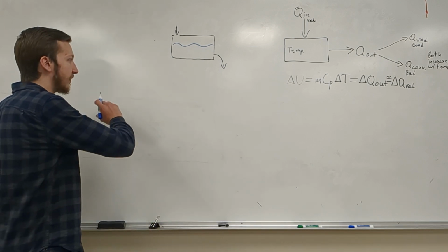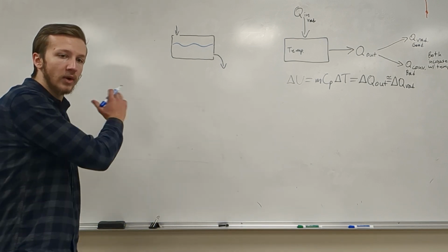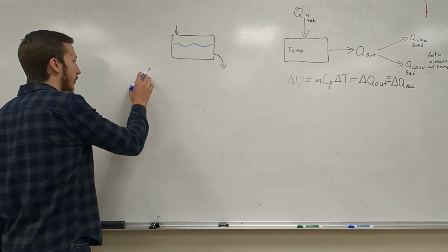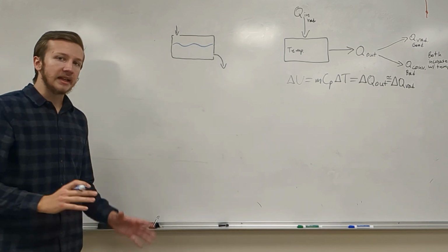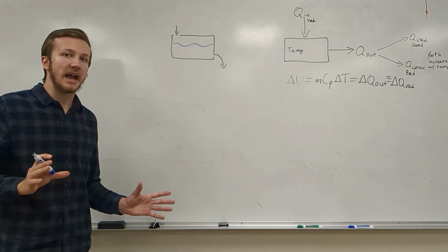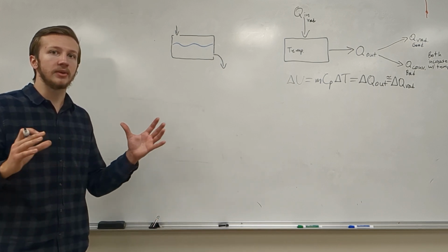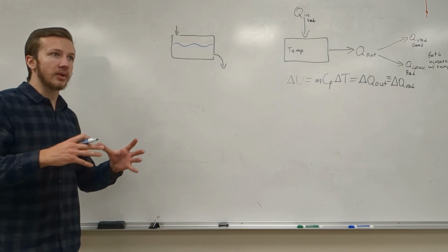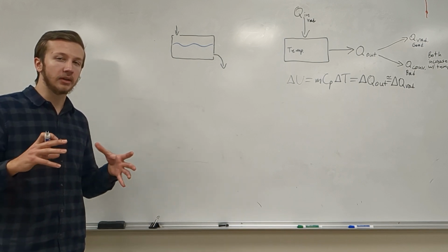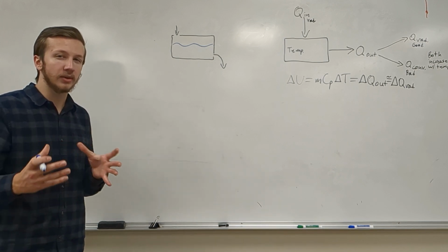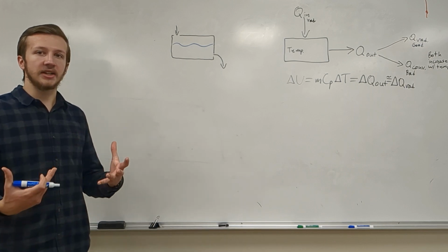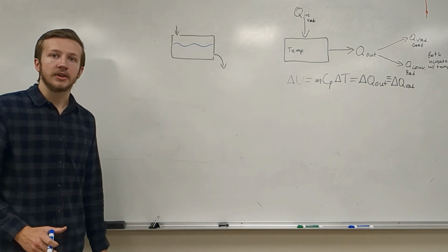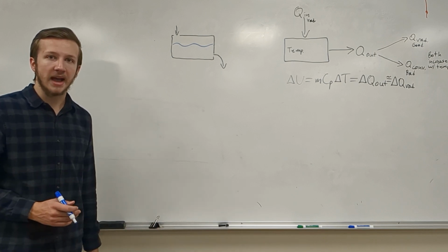first of all, we have to divide the slope that Excel gives us by 1,440 to get our units of degrees Fahrenheit per minute. And then since our two concrete structures have different masses, we wanted to do this on a per unit mass basis. And since concrete buildings are extremely large, and because it gave us a little larger number that's easier to visualize, we decided to divide all of our slopes by tons so that we could have it in a per unit mass basis.